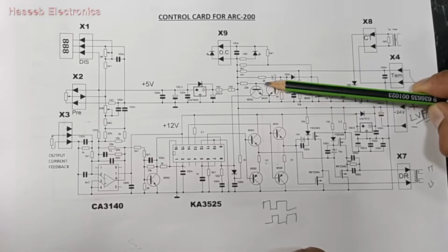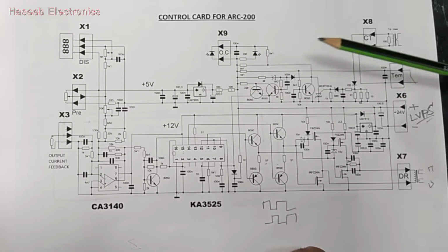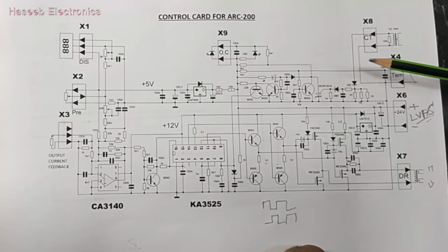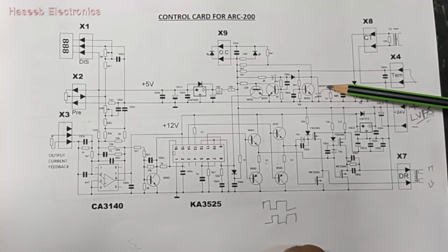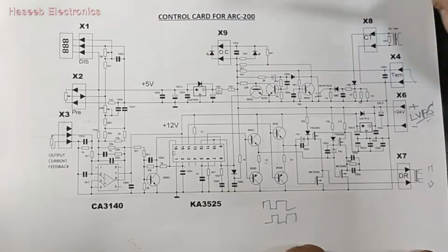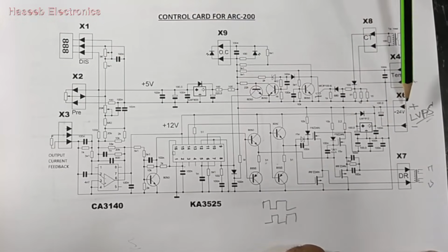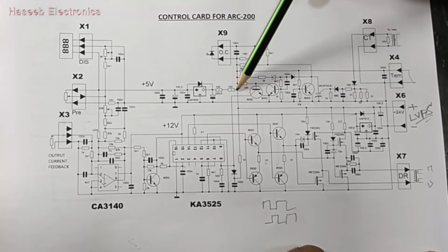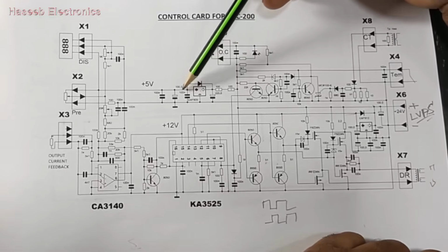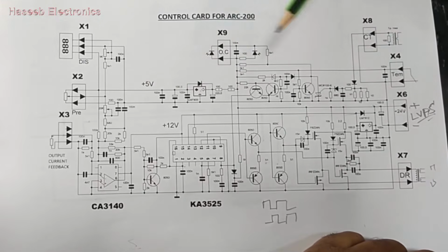Here we have the soft start control circuit. This is the temperature sense circuit, and this is the OC switching circuit, the overcurrent switching circuit. First we will see this circuit. We applied 24 volt from this line to this 7805 IC, and we are taking 5 volts.